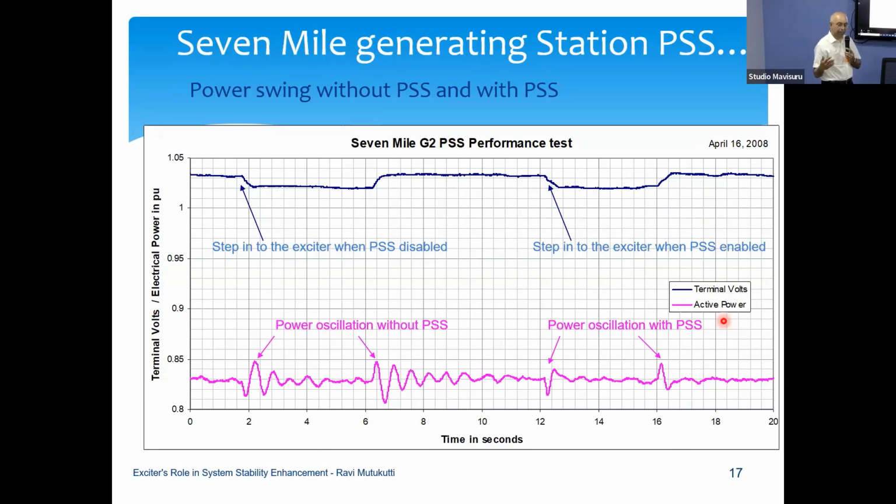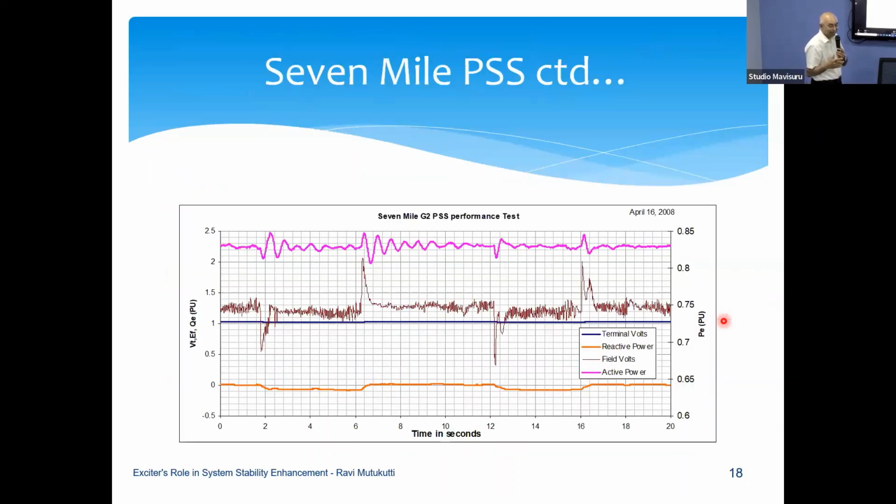The people who are behind IBR do have a good intention of putting megawatts into the system, but sometimes they undervalue the mitigation measures and the cost of mitigation for the utility, and sometimes they might not know about it themselves. So from your side, instead of saying no, you should explain why it is no. Most of the time, no is not an option. You need to tell them this is the cost to us. You might need to run a synchronous generator plant or a static compensator in order to absorb the higher penetration of IBR. That costs, and that cost needs to be reflected in the power purchase agreement. I'm only expressing my opinion, right? I'm not political or anything, so I'm sorry if I offend somebody.